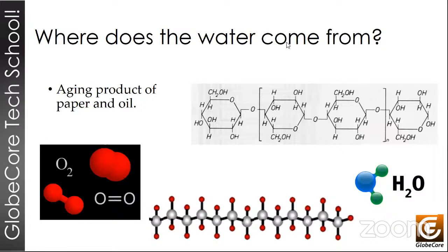During oxidation of oil, water forms as a byproduct of that reaction. And in this case, there is a certain advantage: oil has high solubility of water, so it doesn't result in free water, but oils with high moisture content can foam when we degas the oil.